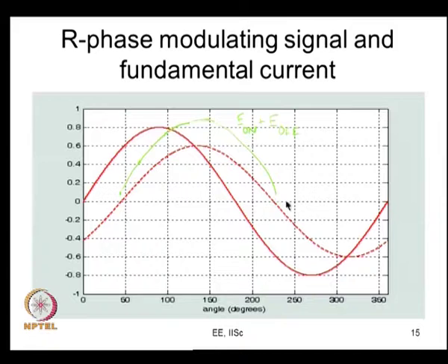Now, what will happen again here? It will be the same thing. The current may be reversed, but what does current reversal mean? Here one transistor and the other diode are conducting. Here the other pair of transistor and diode will conduct: if the top transistor and bottom diode conduct here, the bottom transistor and the top diode will conduct there. So, it does not matter. How would E on plus E off vary? This will again vary something like this, and this would again vary something like that.